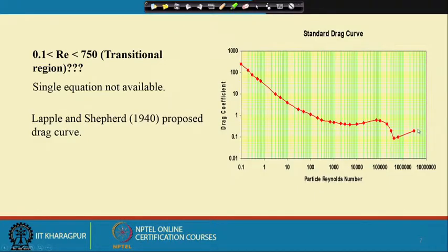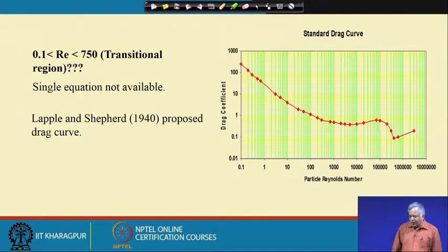Now, this curve is known as the standard drag curve. Why is it called the standard drag curve? The chemical engineering fraternity in particular, and the fluid mechanics community at large, have accepted this curve as a standard one, based on which we will compare the different models.